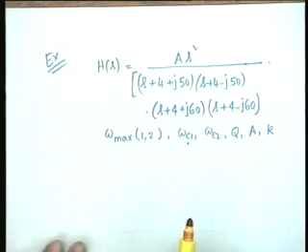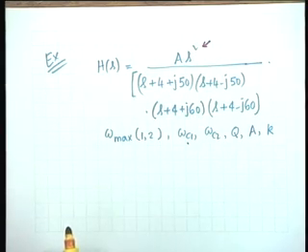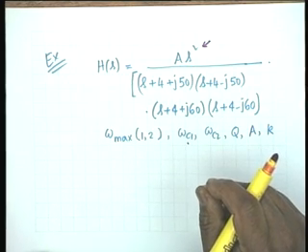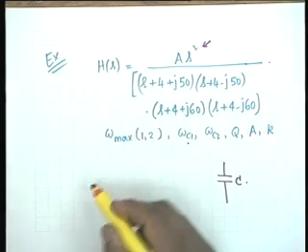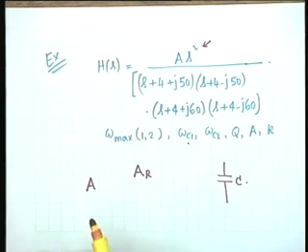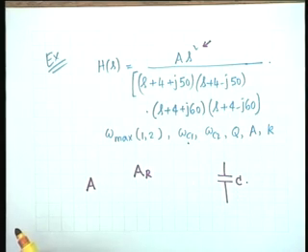The first observation that you make is that the power of s is 2, s squared. Obviously, if it is a double tuned circuit, the output has not been taken across the resistor. If it was taken across the resistor, the power would have been 3. So one power has been reduced. What does it mean? Capacitance. So the output has been taken across the capacitance, which means that the value of A here would be related to the previous value of A, which you shall denote by A_R, if the output is taken across R. How will these two be related?